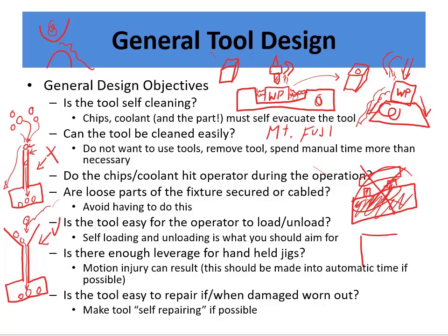Okay, but if instead I make it so that those rest buttons are separate pieces, and then those pieces fit maybe into holes in the part, or I can take them in and out. If one of them gets damaged, I just throw this out and I don't throw the whole thing out. So the good news here is if you make something that's in multiple pieces, you can usually throw out or take apart and throw out the one piece that you don't want to use anymore, that's worn out.